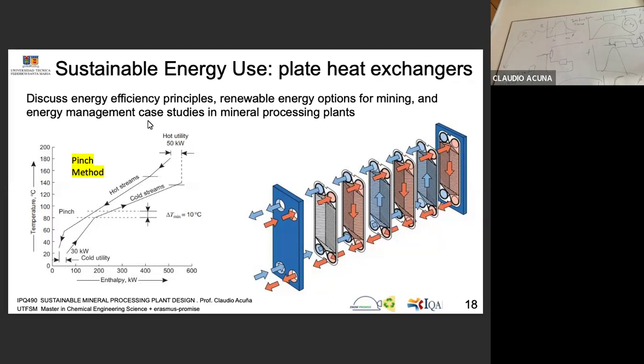So then we use those equipments, and what we want to do is look for the energy flux and also the temperature. You play with different equipments, and we look at the pinch method, because here, for example, I can integrate these two equipment. And this is the pinch method. You have implemented that also in Aspen. So you design a circuit, and then you have hot and cold currents, and then you plot like that. The method is called the pinch method. And then you put the heat exchanger, and you recover energy. And if you recover energy as a balance, you're reducing the amount of energy.